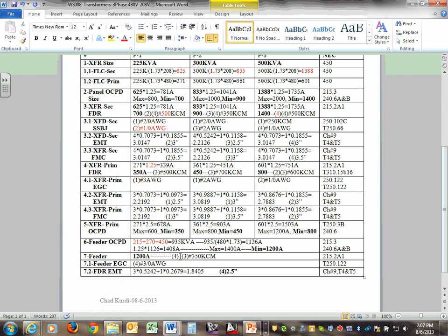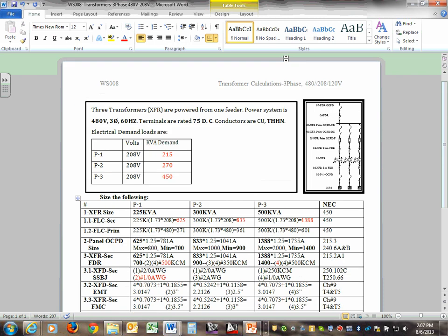Look at the differences: 1400 amp versus 1200 amp, a major difference. I would use the 1200 amp because there's so much diversity in the load. Then you size your overcurrent protection device at 1200 amp, and your equipment and conductor, as well as the conduit coming to this feeder. Any comments, guys? Any questions? I know it's a little bit complicated, not too much though.